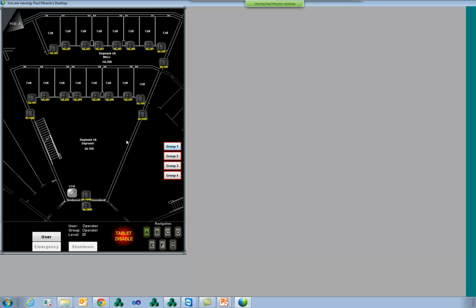With the groups assigned by the PLC that we'll read through the driver sheets here, we can assign groups as far as what we can control. As you can see, these doors in this certain pod are brighter in color, and I'm able to select the doors here. The ones up here in the darker color are a group that I currently don't have control of, so I can't select the doors. I can only view the status of the DPS, door position switch.